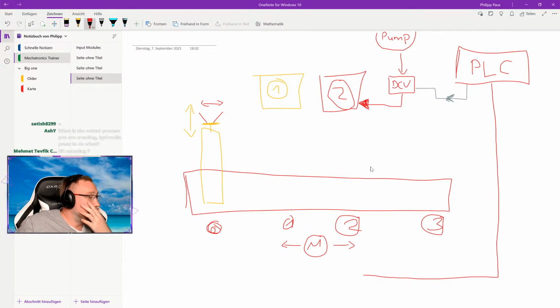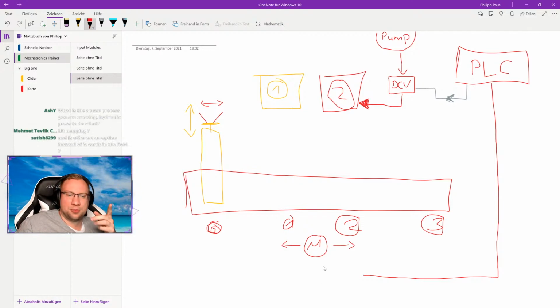So I'm gonna work on something else first because I will need it. There's still a lot to do here. So the motor can go left and right, and as it is an electric motor, a three-phase motor, I want it to be able to go between those two connections. Is it called star delta? I want a star delta starter. So I want a whole motor circuit on this to go left and right.